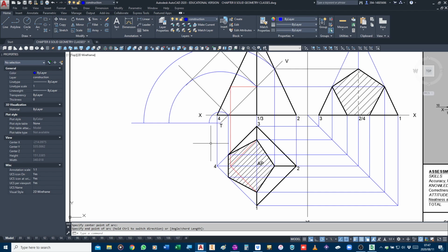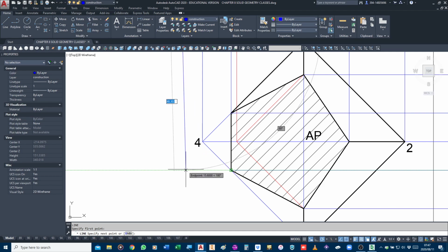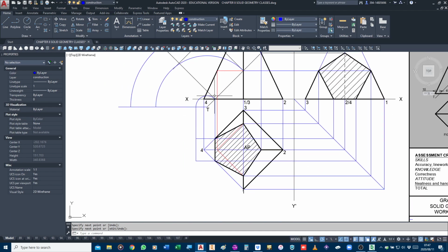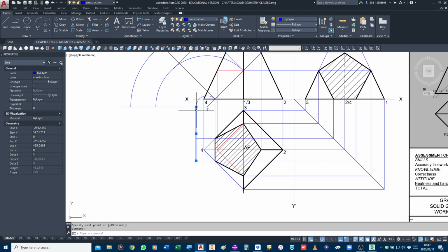From there, it is now just a question of I need to project this to the lines corresponding to those lines. So this point here corresponds to that point and that point on my cutting plane. So I drop that one perpendicularly down and I project to them.